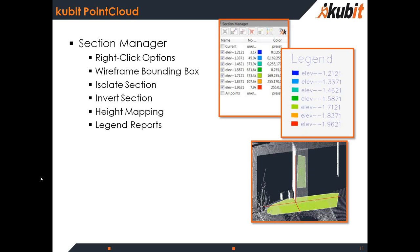And as you can see here in the snapshot on the right, we have the ability now to create a legend that you can place in your drawing. If you'll notice, this is the snapshot of the section manager here. If you have the sections with different colors, then you just highlight the sections and click the legend button. It'll actually place this legend here in the drawing, complete with the name of the section, which in this case is delimited by its elevation, as well as the color code that matches that.